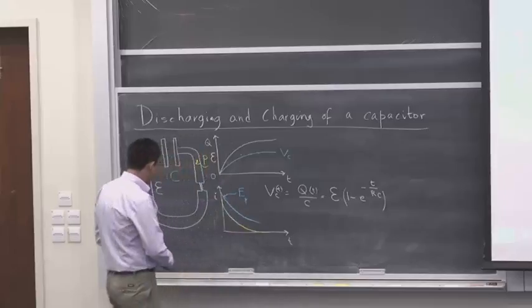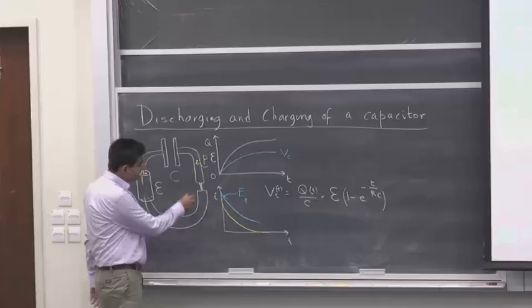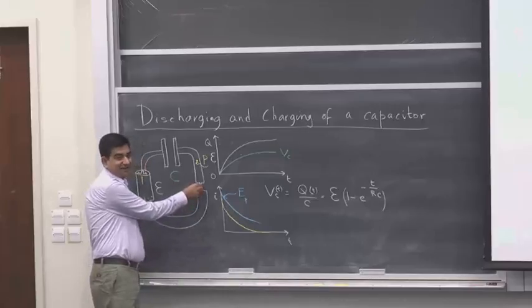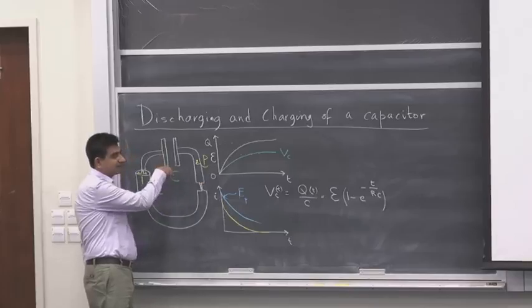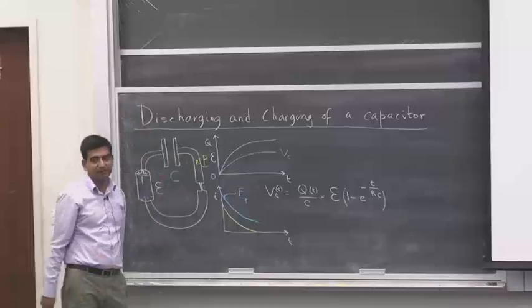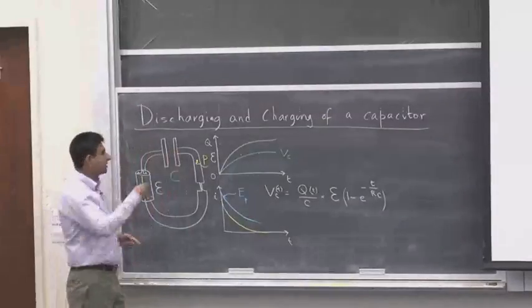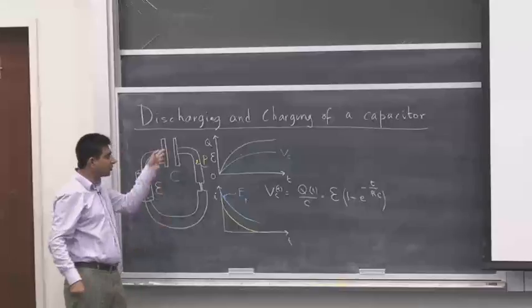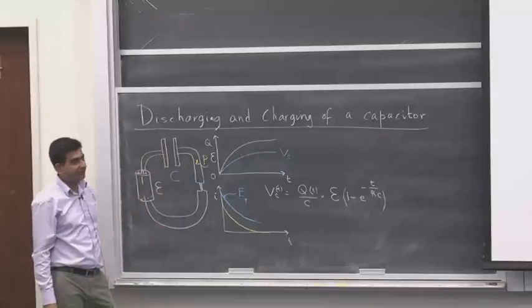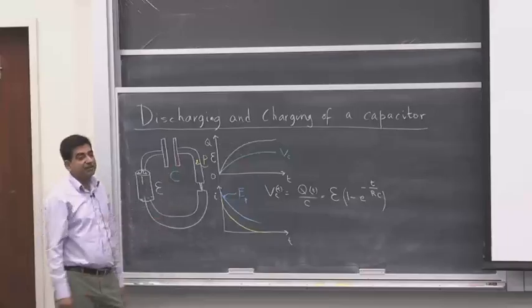So if I were to use a bigger resistor, which means a thinner wire here, a thinner and thinner wire means a bigger resistor, or if I were to use a capacitance which is large, say large capacitors, or capacitors that are really close together, or a capacitor in which I inserted or poked in some dielectric. For such circuits, the buildup of charge is going to be slow.